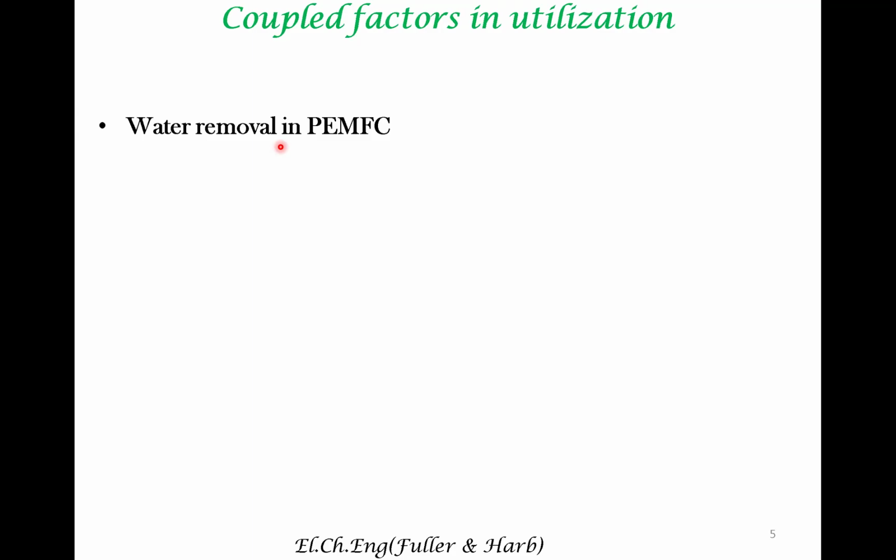But if you remove a lot of water, as you know, in a PEMFC the electrolyte contains water. The conductivity of the electrolyte crucially depends on the amount of water present. If the membrane gets dried out, it significantly decreases the conductivity of protons. So that is also not desirable.